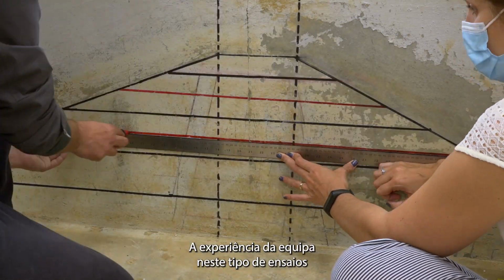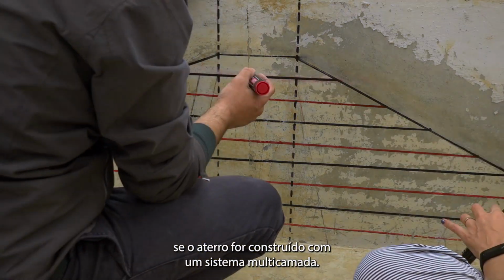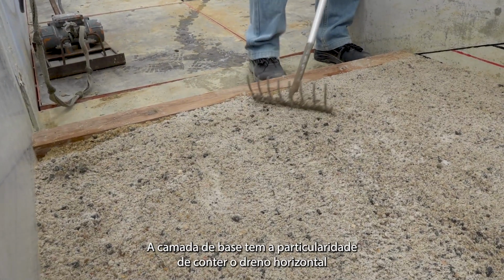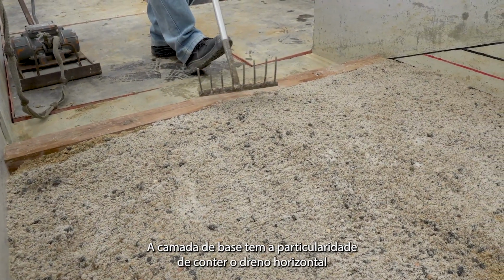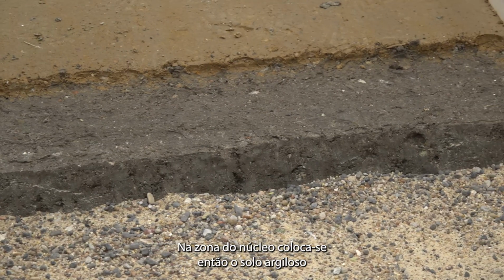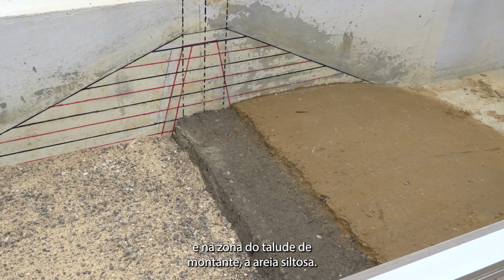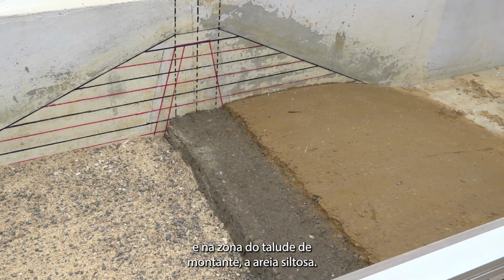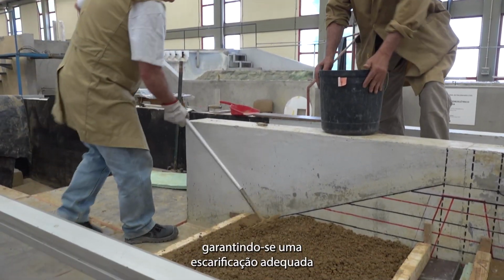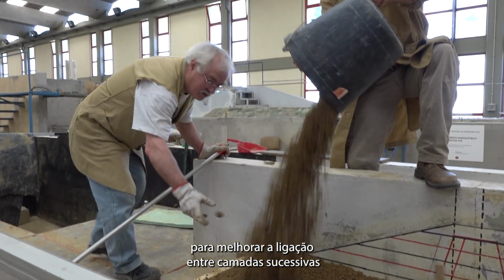Experience dictates that uniformity and homogeneity can be achieved if the embankment is constructed with a multiple lift system. The first lift has the particularity of containing the horizontal drain across the dam's downstream slope. In the remaining parts of the dam, clay and silty sand were respectively placed in the core and upstream slope. The remaining lifts are compacted one after the other with adequate scarification to improve binding of successive lifts.